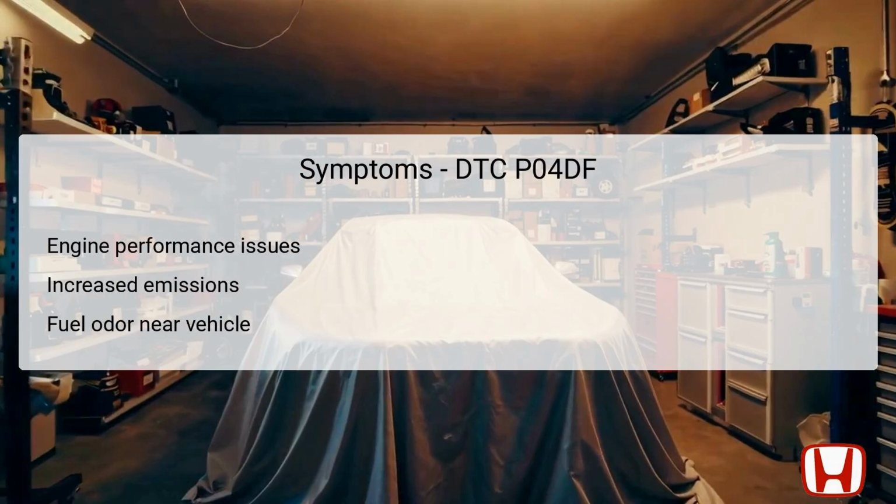When the DTC P04DF is present, drivers may experience several symptoms arising from the malfunctioning EVAP system. One of the most common signs is engine performance issues, which may include rough idling or increased engine stalling. These problems occur because the proper vapor flow dynamics are not maintained, leading the engine management system to miscalculate fuel mixture. Additionally, increased emissions will often be noticeable as excessive fuel vapors are not being managed correctly.